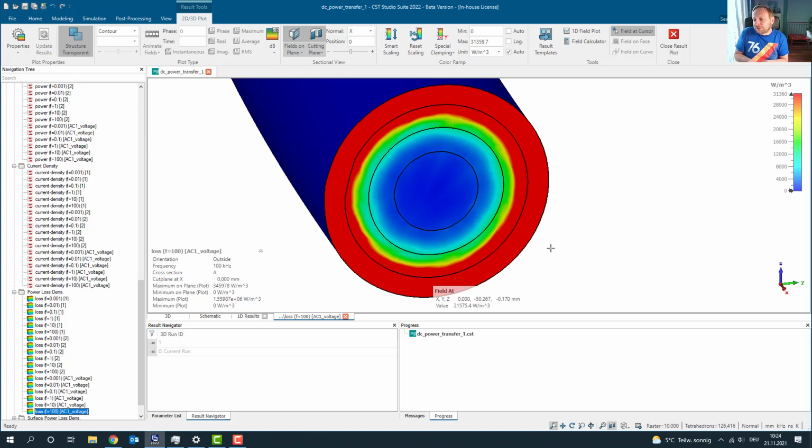So I think it's really safe to say that the energy traveling from the source to load is really inside the space, and even if the fields penetrate into the conductor, they have a very different direction and only lead to the loss mechanism. So skin depth actually does not play a role in the energy transfer, it just plays a role in how the loss will be distributed inside the conductor.